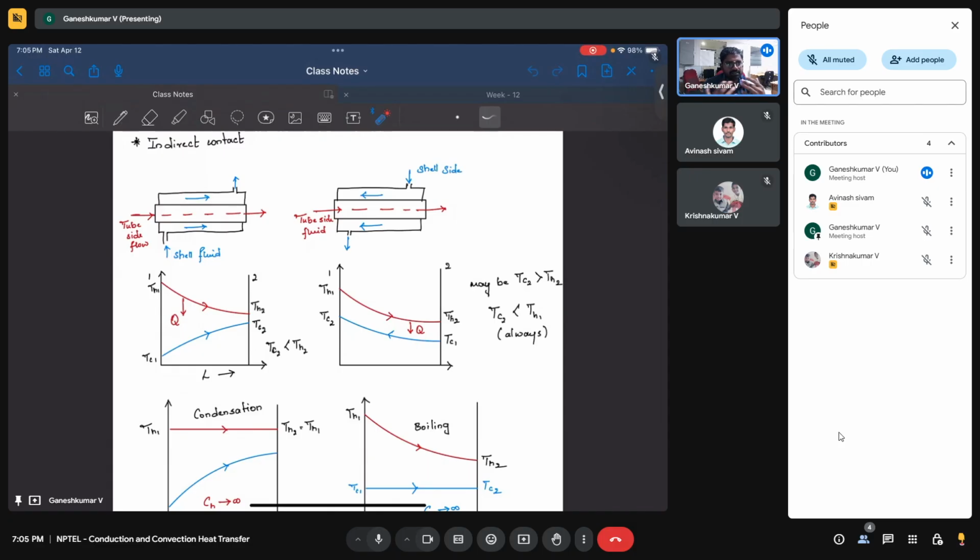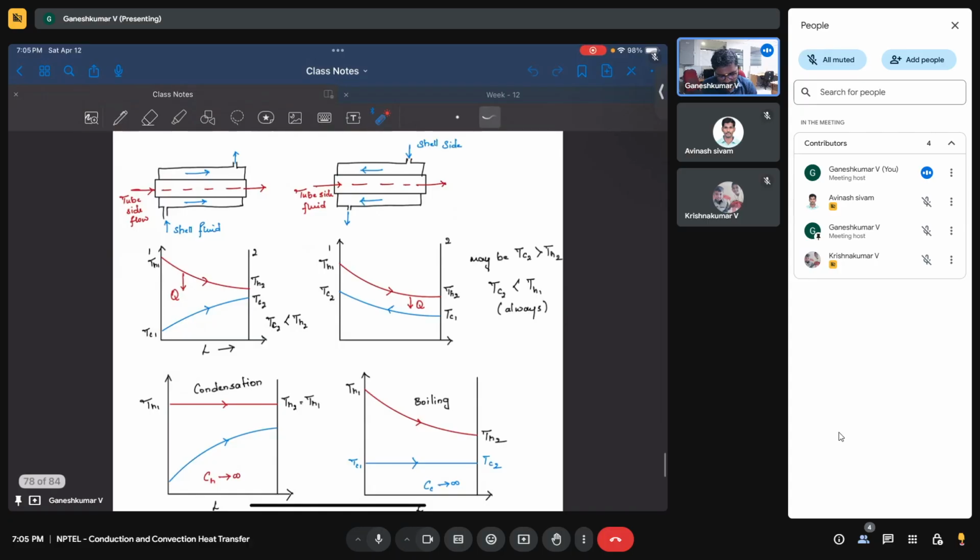A heat exchanger is basically exchanging heat between a hot and a cold fluid. We want to either cool our fluid of interest, or heat it up, and we do that with another fluid at a different temperature. For example, in a shell and tube heat exchanger, you will have a shell, and inside it the tube, and in the tube the hot liquid will be flowing, and outside the tube the cold fluid will be flowing, and the tube wall is what the heat transfers across.